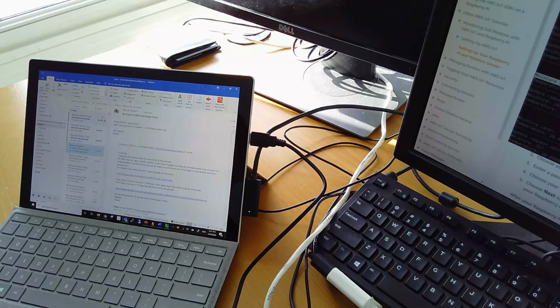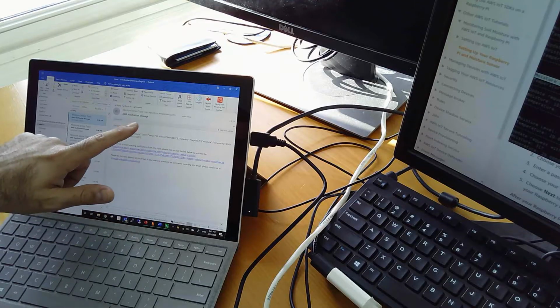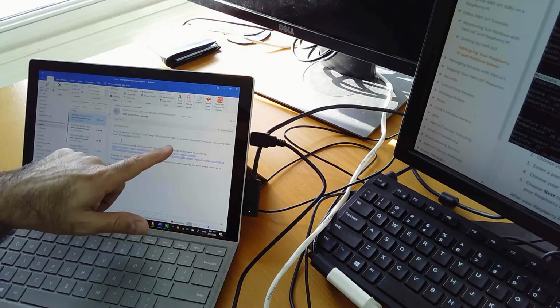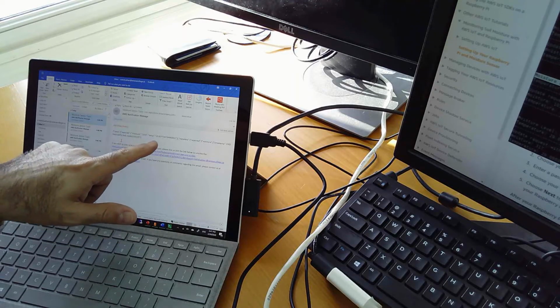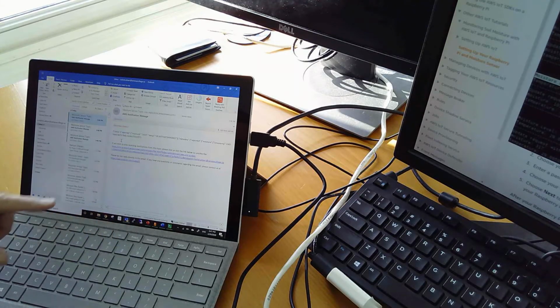So I have 3 emails, so let's open one of them. As you can see, the state is reported, moisture is 1015, and I received 3 emails because of those 3 readings that are above 1000. I have moisture here, temperature, metadata, and the option to unsubscribe from these notifications. I received these emails because I went above that 1000 threshold.